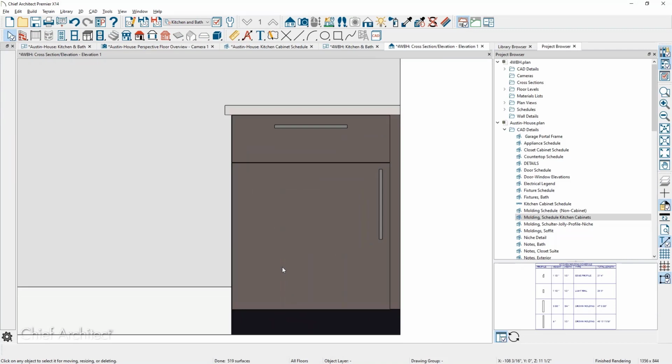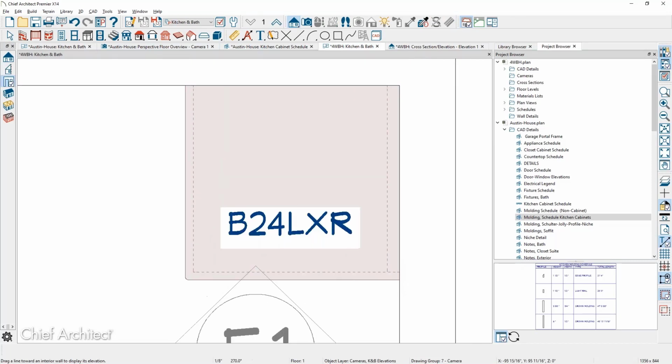That's correct, yes. I was using the temporary dimensions, which can sometimes be very difficult to click on, especially if you have a lot going on in that kitchen. So those can sometimes be really difficult to use. So I've been using either a CAD line, or I'll just put a filler there and just remove the filler. Yeah, that's a good one. I like the idea of maybe just using a temporary filler. You could even use that filler and resize it so that it's inside of your cabinet, and use that as a bumping box. Does that make sense?